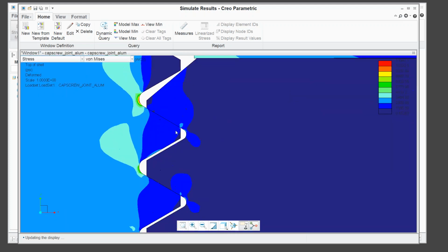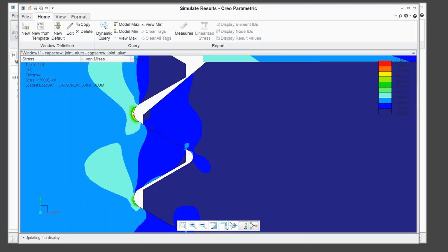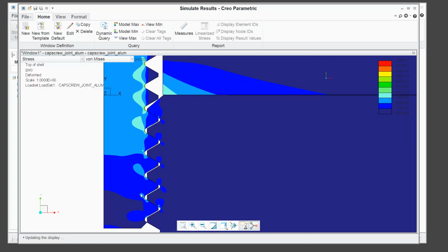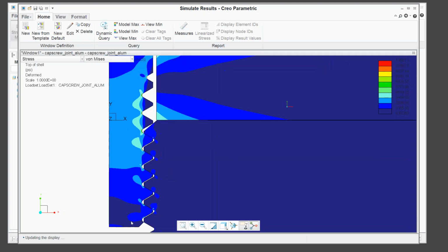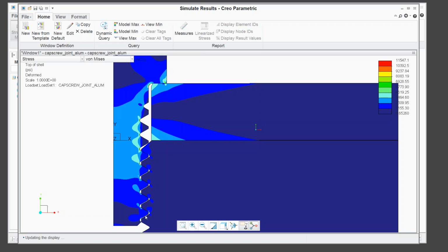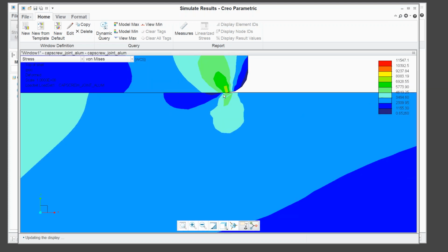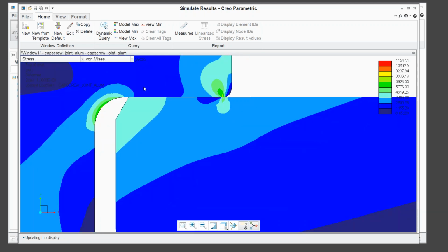And then the other thing we can look at is the stress at the contacts in here, and you'll see that the stress is getting lower as we go down. So the upper threads are deflecting and taking up load, and we're seeing less and less load taken up by the lower ones. And at some point, it's going to be negligibly small. Theory tells you, I think that's around 2 times diameter. The material here is aluminum. The bolt is steel. If this were steel, I think you'd probably see less load taken down here at the bottom. So if you're in a soft material, it behooves you to make your threads a little longer than in a hard material. And then up here at the top, we're seeing contact stress. This, by the way, is typical contact stress, has these little concentric circle shapes.